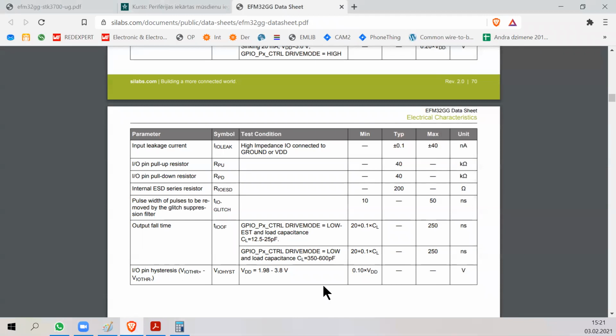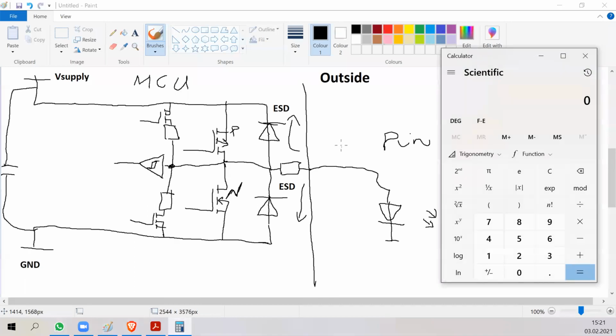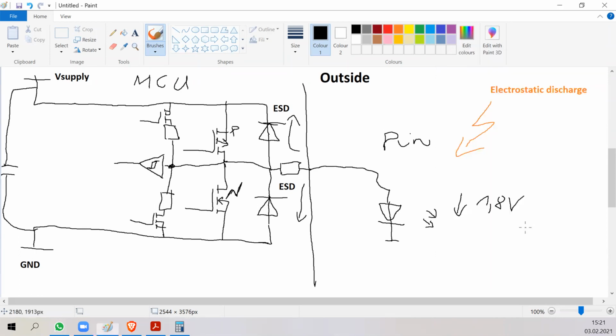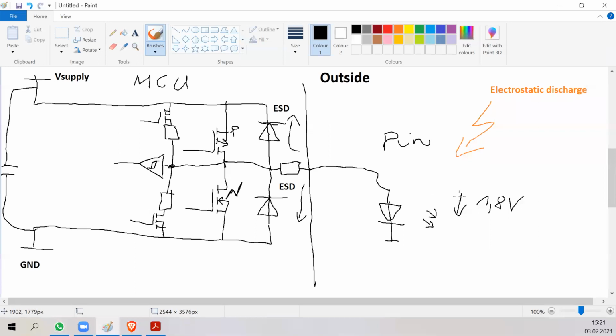And if you are working with LEDs, the voltage on, for example, a red LED is 1.8 volts. So you would also need to subtract that: 3.3 minus 1.8 divided by 40,000 is only 37 microamps. So very small current.